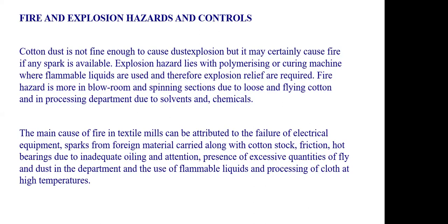The explosion hazards lie with the polymerizing or the curing machines where flammable liquids are used, and therefore explosion relief is required. Fire hazard is more in blow rooms or spinning sections due to loose and flying cotton, and in the processing department due to the solvents and chemicals. The solvents are what they use for the coloring of those cloths.